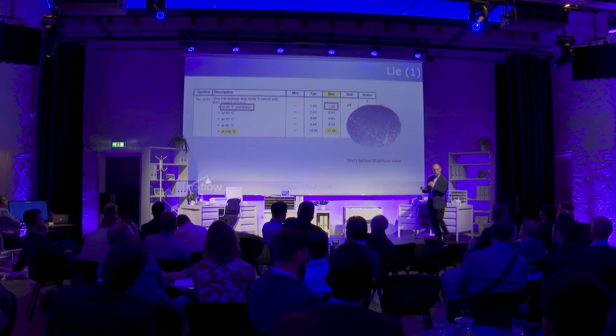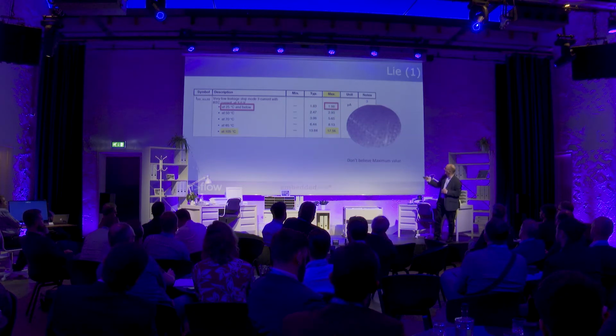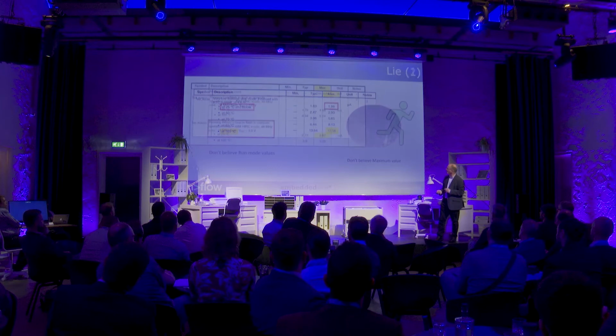So if you're specifying a microcontroller, you're looking for the vendor who's taken the time to look at the intermediate temperature ranges, something a little bit more practical, say 50 degrees, to give you a realistic number, because that might be the most relevant maximum and not this one. So don't believe maximum values.